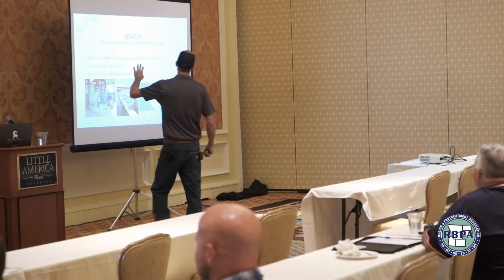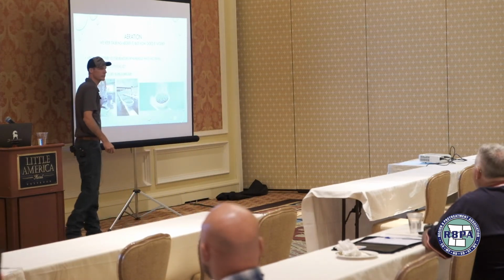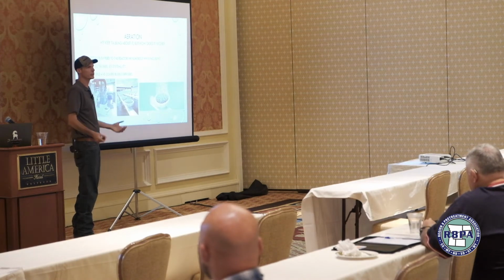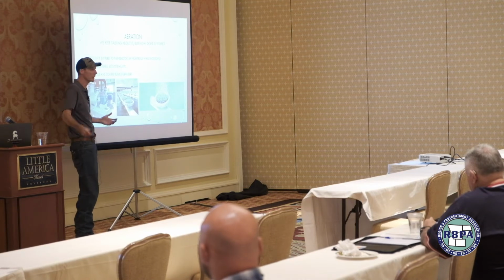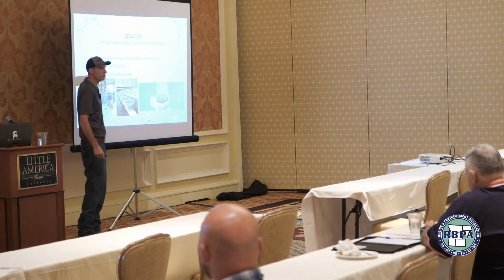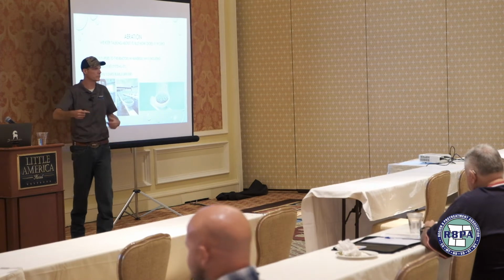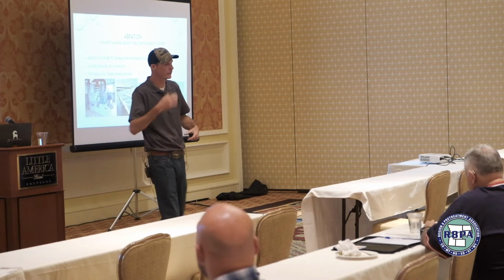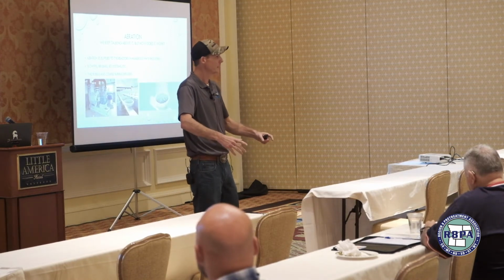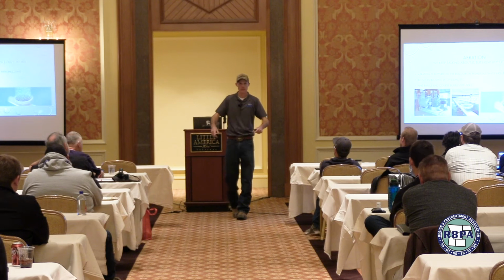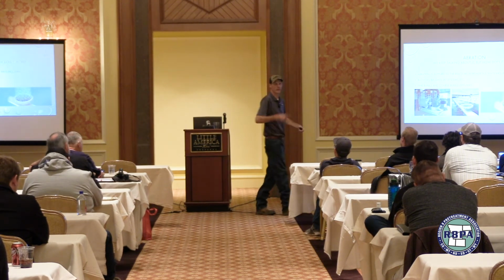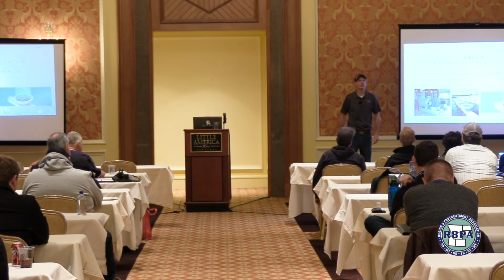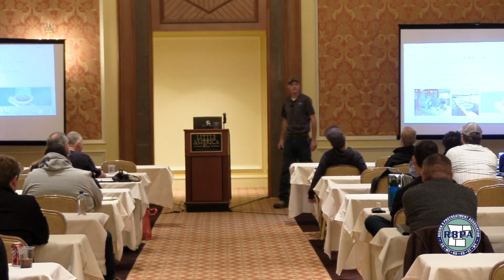Okay, so blowers: multi-stage centrifugals, old school, still work. High speeds are kind of the new technology, super cool technology, but somewhat limiting. I'll talk about brushes. Box Elder has an oxidation ditch made by Kruger, which is basically a motor that runs a giant brush like you see on the front of a street sweeper. Everybody seen a street sweeper? It kind of looks like that. And all that's doing is introducing oxygen, making some turbulence. Jet systems. Anybody ever heard of a jet system? Jet techs.